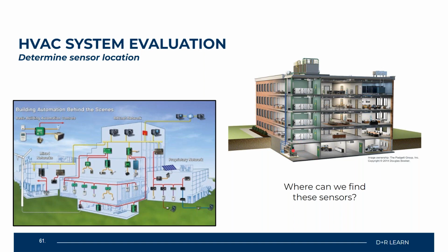It might be too much, and this office here may be complaining that it's too cold. If you have that situation, you're going to have to remedy it and find out how to adjust it. It's also a bad use of, or we could say a waste of, energy to continue pumping cold air into a space that doesn't require it, yet you might have another space that is extremely warm and could use that airflow. So having these different sensors in place will allow you to do a lot of diagnosis on these different systems that you have set up within your facility.